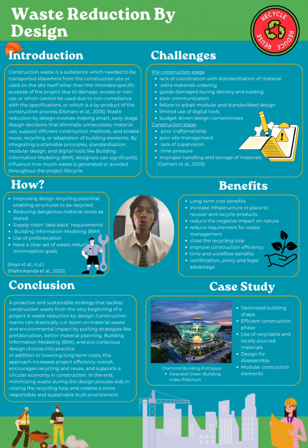So, how do we reduce waste through design? Here are the key strategies, starting with improving design recycling potential. By designing buildings with recyclable materials and components, we enable easier reuse in the future. Other than that, we move on to reducing dangerous material levels. Limiting hazardous substances ensures safer disposal and easier recycling. And then we introduce take-back requirements. Supply chain contracts can include conditions where suppliers reclaim unused material for reuse.